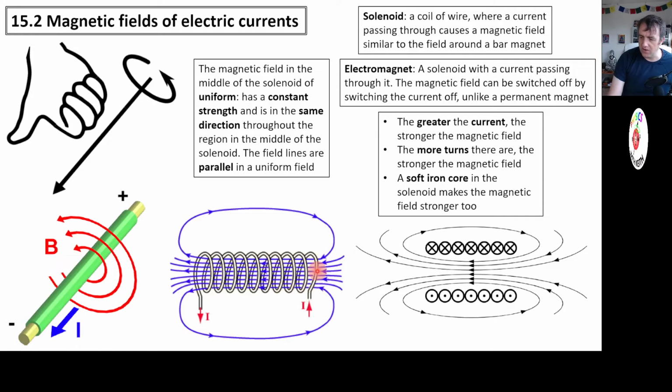So if I place my dot here, the current is going up. So I can take my thumb and point it up. The fingers are going into the middle of the coil. That's the direction of the field. And outside, they'd be going in the opposite direction, which is what we can see here and here. If I take the wire at the top here, the current is going away from me into the board, which I suppose is that way from your perspective.